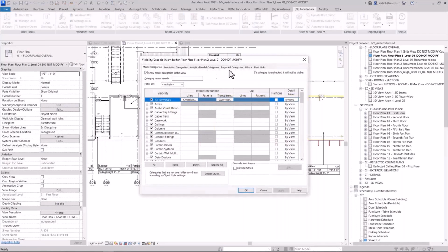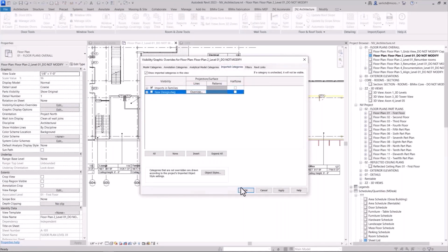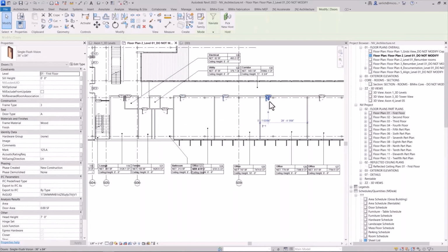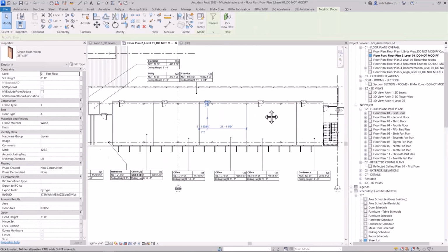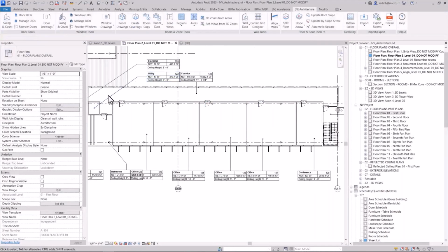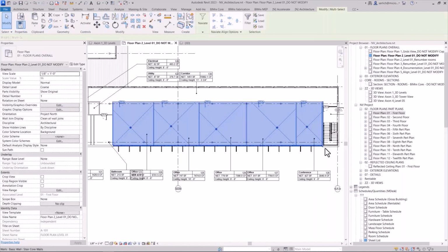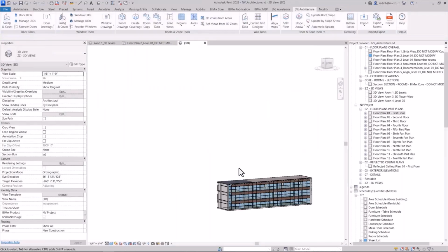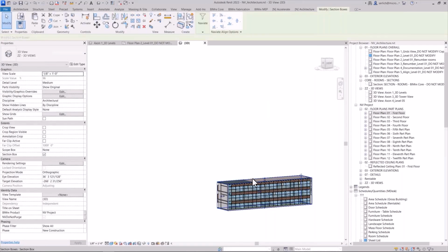doing other things. Let's go ahead and hide that DWG for now and focus on the doors that now need to get updated to the new design. Once I move my walls around, I want to adjust my doors as well so that they're all spaced at a specific distance away from the wall, right? They're kind of all scattered because the walls changed at different distances.